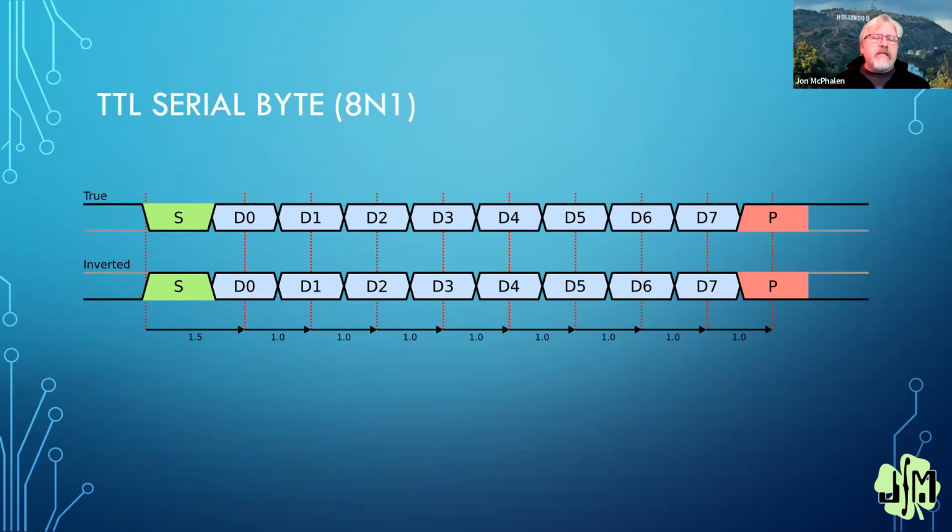With the smart pins, there's a little monkey motion you have to do in the way that I've done it, unless Chip tells me there's a better way: I tell the smart pin I'm sending 9 bits, and I set that upper bit to a 1. So it creates a faux stop bit, if you will. And then that way I can get a little extra time in between so that the receiver has time to deal with that. On the receive side, it's not a problem.